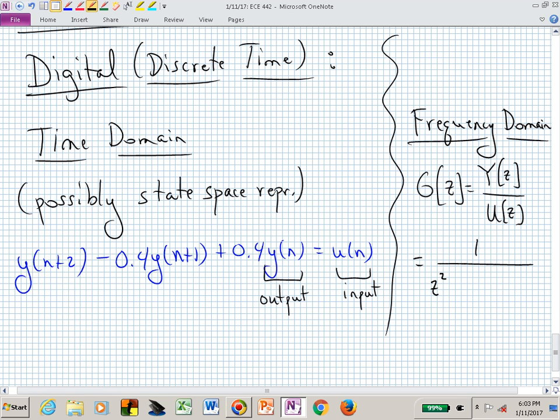So it's a unit delay. In this case, we will be becoming comfortable drawing block diagrams, all delay block diagrams associated with linear difference equations. And in this case, you would be expecting two delay blocks.